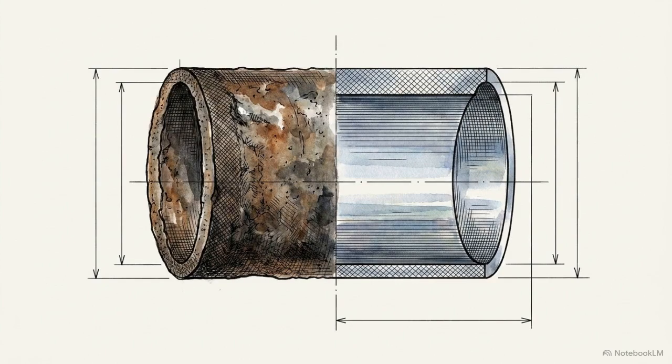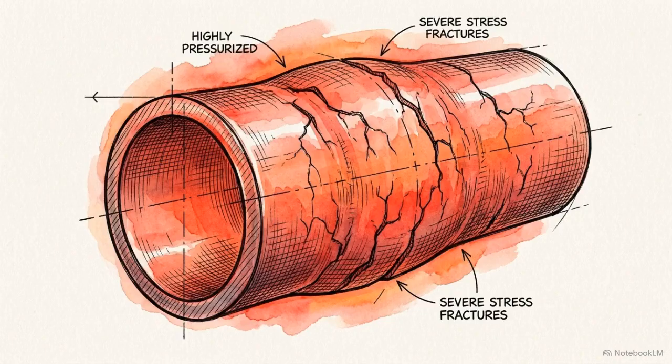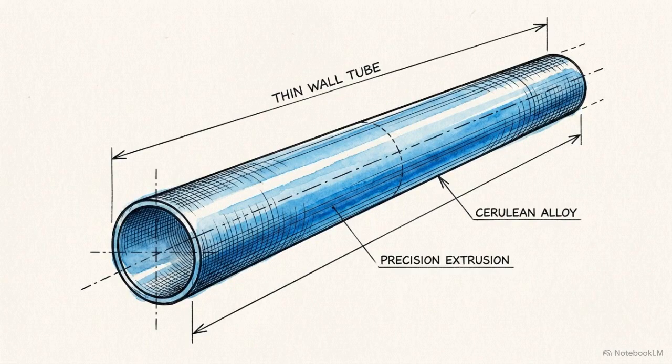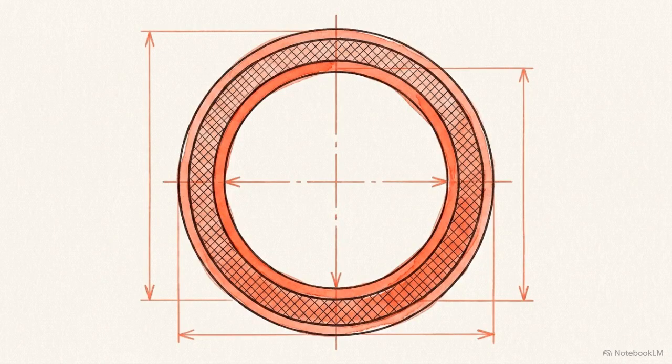You are missing a critical variable, the material's allowable stress. A heavy Schedule 80 pipe forged from a low-strength metal, operating at high temperatures, can rupture before a thin Schedule 40 pipe made from a high-strength alloy. A pipe's schedule tells you its geometry. Until you run the yield strength of the specific material through a formula, its pressure capacity is unknown.